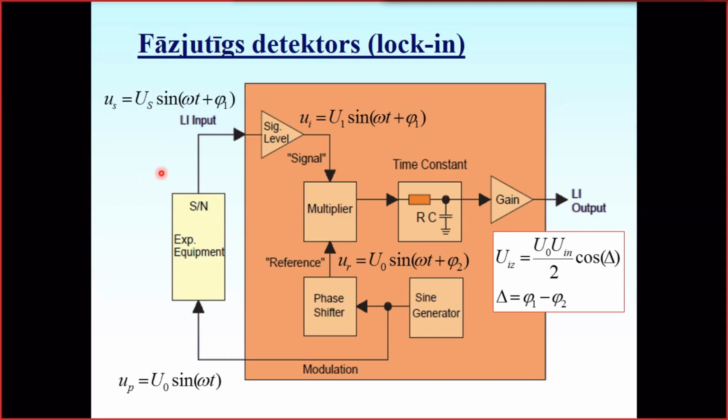The signal we take from the photodiode measuring this laser oscillation will oscillate with the same frequency. The input signal is oscillating with the same frequency. It may be quite tiny, so the amplitude may be very low, and it is usually compromised with an amount of noise. So the signal that comes to the input of the lock-in amplifier is usually the useful signal at a certain frequency omega, and a huge amount of noise of all frequencies.